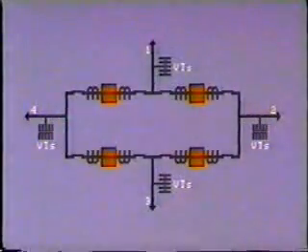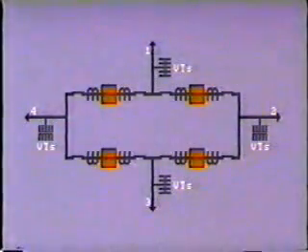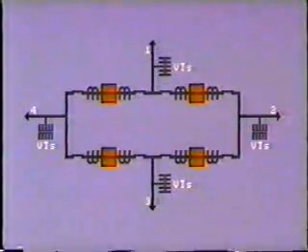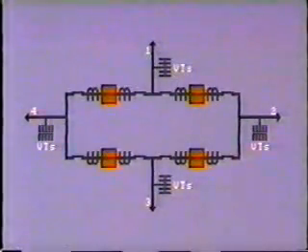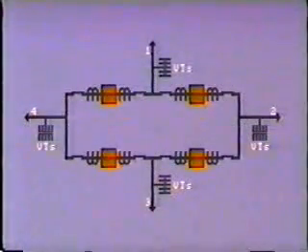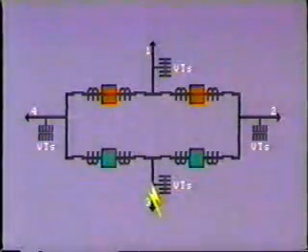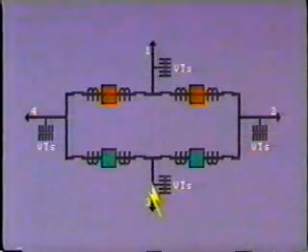Another bus arrangement commonly used is the ring bus, like this. Here we have 4 circuits connected to a common ring, which in turn is broken into 4 sections by 4 circuit breakers. A fault on any line will cause the tripping of the 2 breakers on either side.